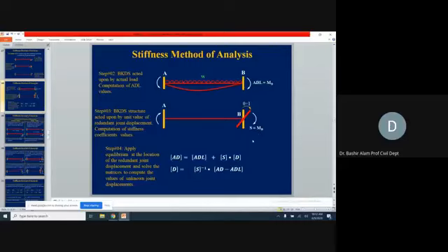So at the near end and at the far end, when we know the moments, what we can do, that is becoming our total unbalanced moment. We need to keep the structure in equilibrium. So what we do now, we apply a balancing couple. The balancing couple direction will be opposite to this applied unbalanced moment, and its magnitude will be simply the summation of this unbalanced moment divided by the distance between the two ends.